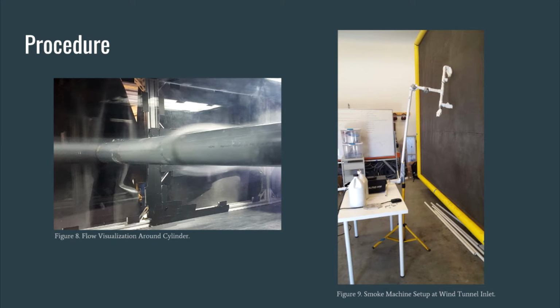The team began this experiment by conducting a formal safety check and clearing the tunnel of any loose debris that could inhibit testing per the safe working procedure. While this was completed, team members also collected ambient temperature and pressure readings. A sample rate of 100 readings per pressure port per data collection period was selected within the scanning valve interface. At this time, a full set of wind-off pressure data was recorded without the wind tunnel running for calibration purposes.